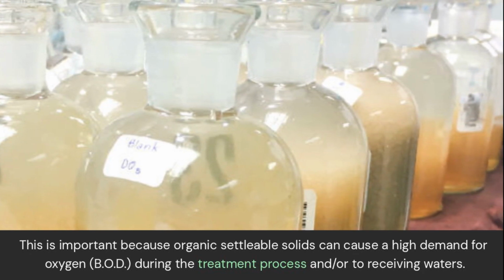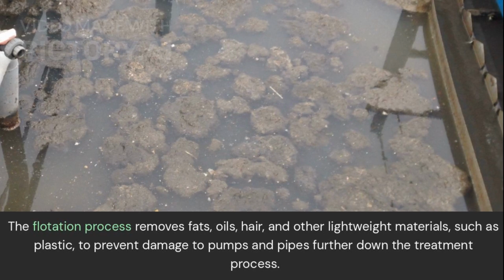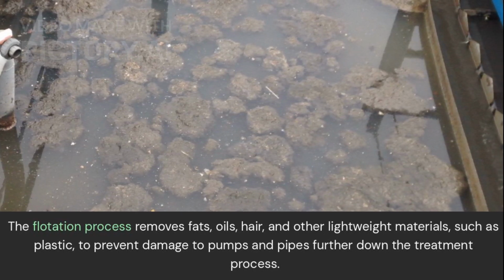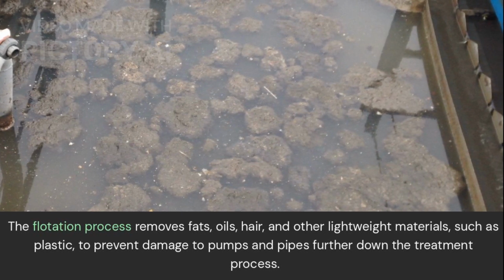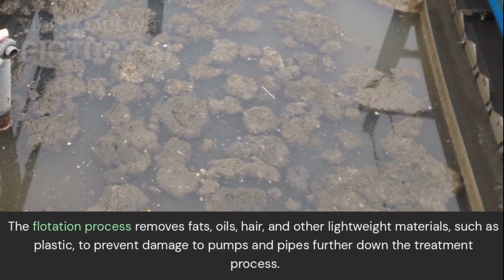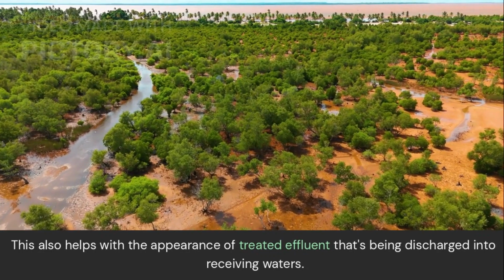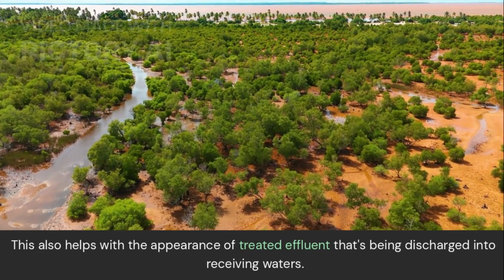The flotation process removes fats, oils, hair, and other lightweight materials, such as plastic, to prevent damage to pumps and pipes further down the treatment process. This also helps with the appearance of treated effluent that's being discharged into receiving waters.